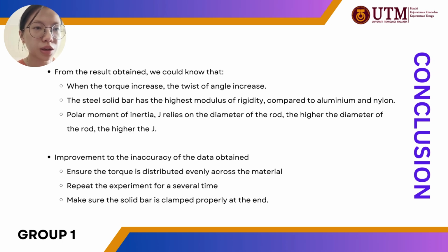To improve the inaccuracy of data obtained, firstly, we have to ensure the torque is distributed evenly across the material. Secondly, we have to repeat the experiment several times. And lastly, make sure the solid bar is clamped properly at the end.